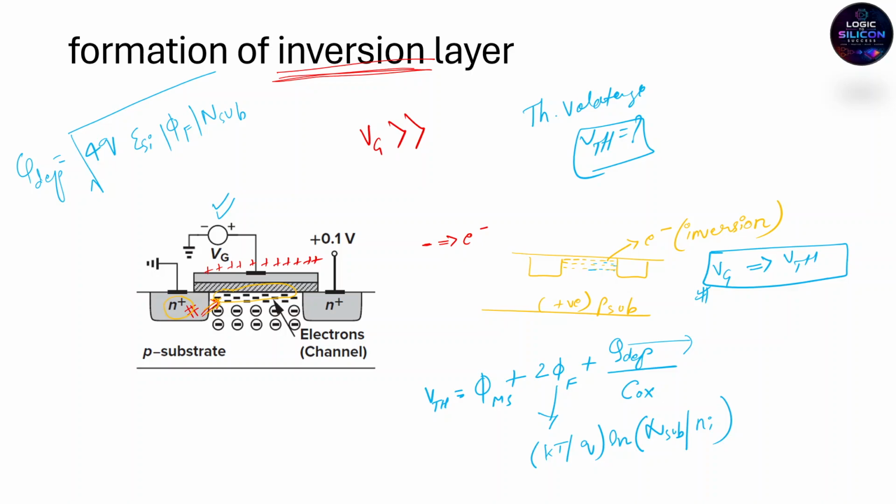For this reason, the threshold voltage is typically adjusted by implantation of dopant into the channel area during device fabrication. In essence, this alters the doping level of the substrate near the oxide interface. That is the whole purpose. Hope I am clear with this definition of the threshold voltage.